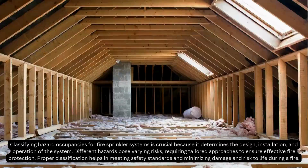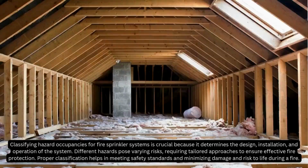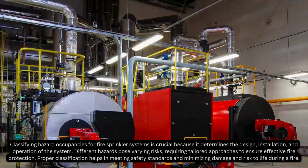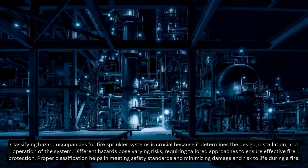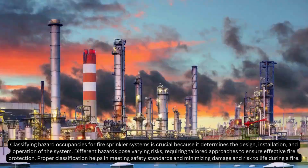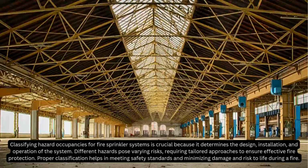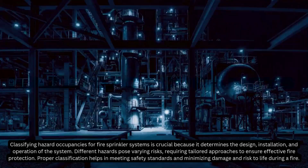Every space, from quiet offices to busy restaurants, from data centers to warehouse storage, carries its own level of fire risk, and that risk shapes how the sprinkler system must be engineered. Hazard classification isn't just a formality. It defines head spacing, pipe sizing, system type, and how much water needs to flow when seconds count.